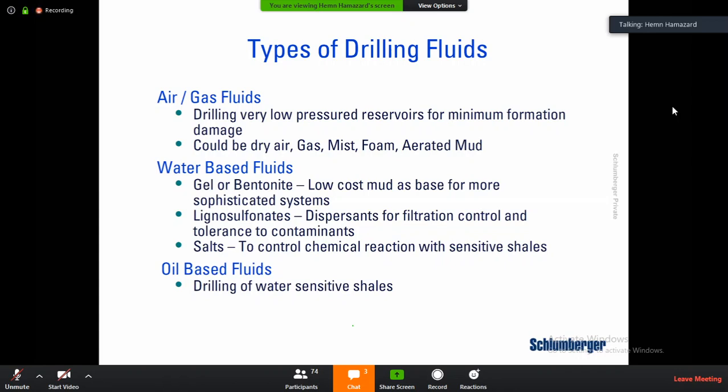In my experience, we have drilled through some sections where the torque was at the limit. It was so high to rotate, and the string has a limit for the torque. If you exceed that, you're going to break your string. So if you have no choice, you have to pump some lube or diesel. We have also pumped diesel or some lube just to reduce the torque by increasing the lubricity.